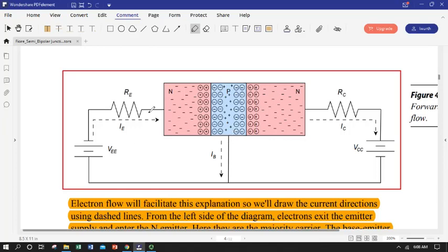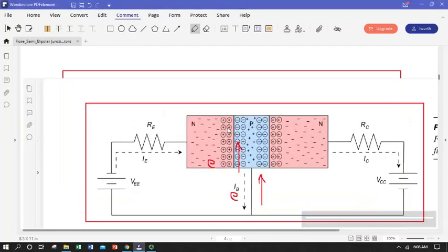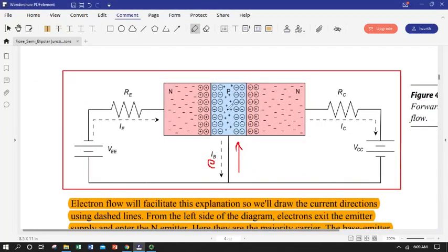But the fact that we have charge coming from the emitter to the collector not getting recombined in the base means that any charge we inject into the base helps the journey of charge going across. So the base current, whichever direction it's flowing, and conventional current can only flow this way, electrons are flowing in that direction, but the more charge we put in the base in the correct direction, the more we enable charge to flow across the device. We make it easier for these electrons going across, or positive charge going the other way, to make it across.